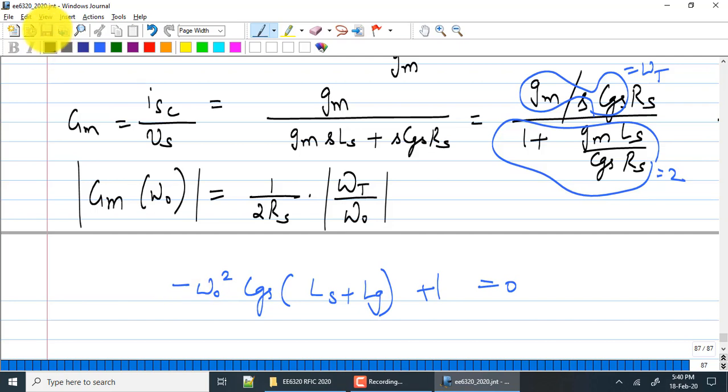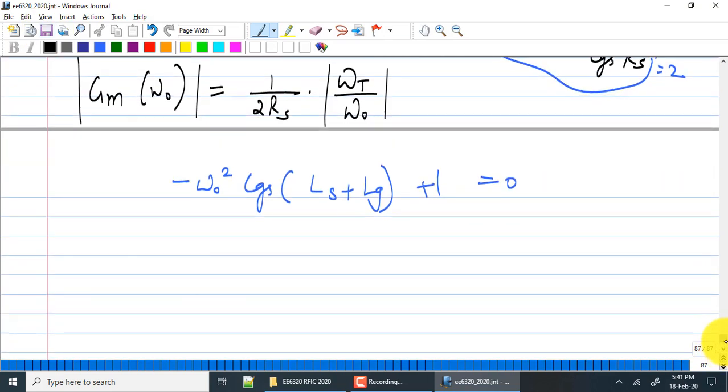Okay. Any questions? So now all we have to do is take those two noise sources, divide it by the GM and apply noise figure equation at the input directly. Right? That's a lot easier.